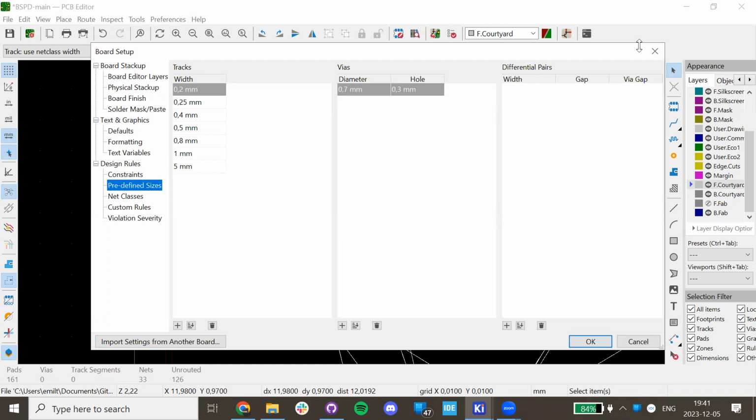The resistors we use, for example, are so small that you should always check, like an 0603 resistor can never handle more than 0.2 or 0.25 watts, I don't remember. But you need to check that your components, if you're doing a current division, are not consuming more than that. Think about that for flyback diodes as well.